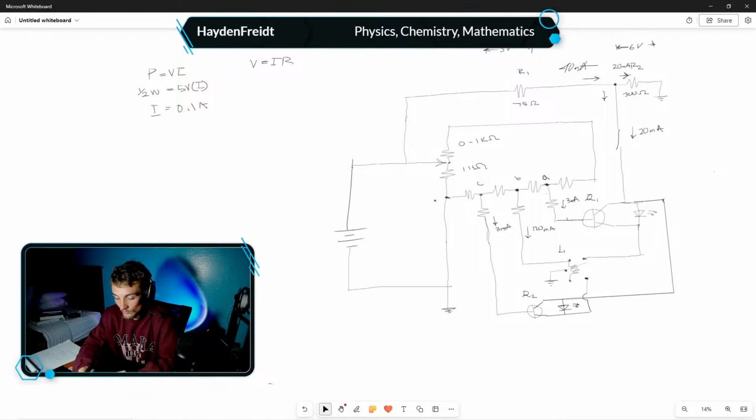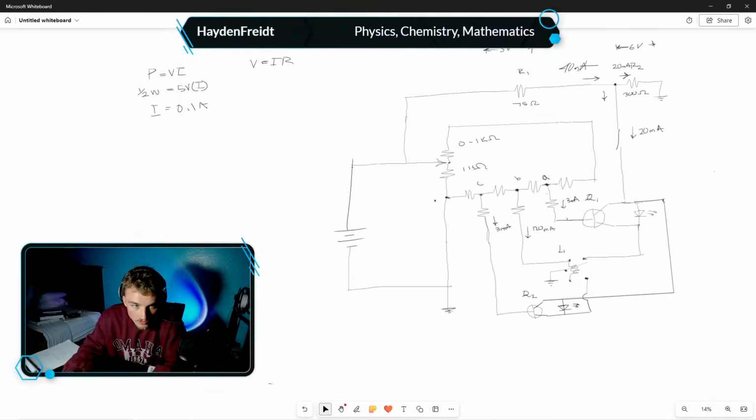and that's going to give us 9 milliamps. Okay, but we're going to want 9 divided by 100. I mean, we could go even smaller, but I don't know that I have any smaller potentiometers than 100 ohms, so let's just roll with that. But again, as we increase the resistance, we're going to get a smaller current. As we decrease the resistance, we're going to get a larger current.